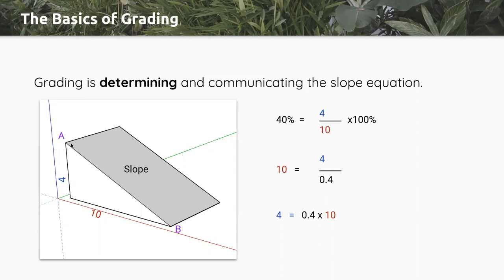So you pick the 2 points, you measure the distance, and then you give it a height difference of 4. What is the slope between those 2 points? Or if you give it a slope like 40%, figure out what that run is. Or you can do 1 dot on a piece of paper, choose the scale, slope and height, like 2% for 2 feet or 2 meters, and figure out the distance to the next point.